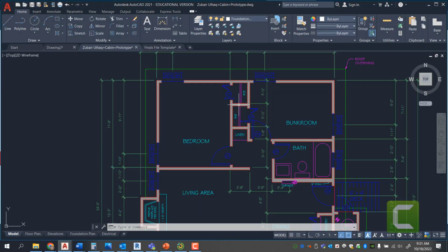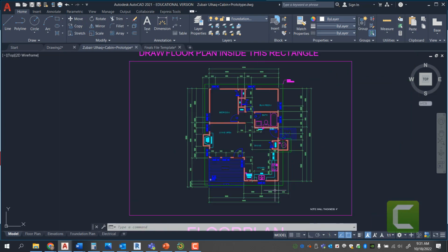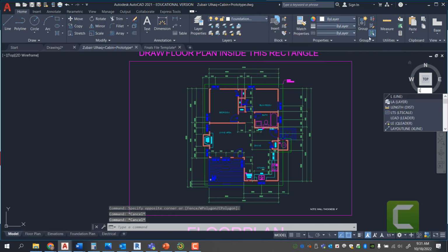The way you use layers is you can actually take a drawing, and let's say you have placed everything in one particular layer. I can go ahead and turn off the dimensions on this particular file. So I would just select the layer, and I know this is in the dimension layer. I'll open up my layer properties by typing LA, or I can click on layer properties under the Home tab, Layer panel.